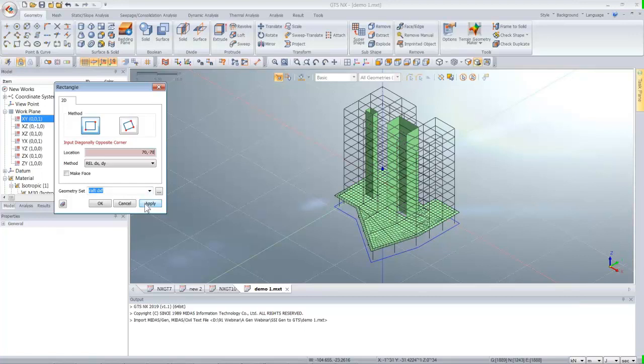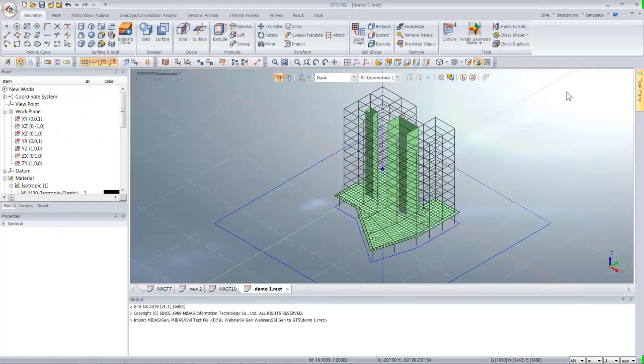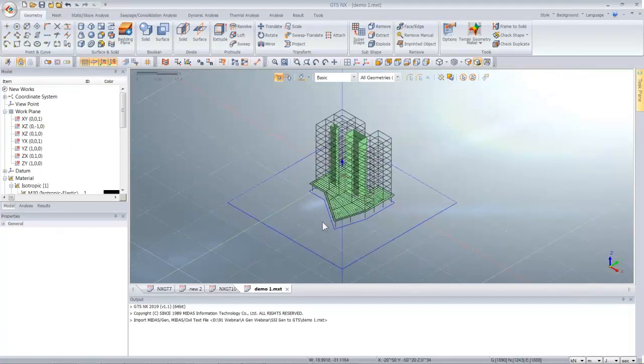It's always a good idea to simulate your 3D structure firstly as a 2D. If it is possible, you can firstly make it as a 2D and then you can use the extrude command to create a solid geometry out of it. So it becomes very easy for us to create the 3D structure using 2D simulation first. Okay, so I've created the 2D raft outline and I've created the 2D soil outline. Now I can go ahead and use the extrude command.